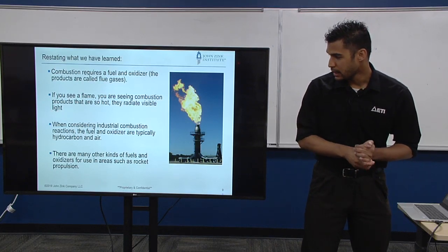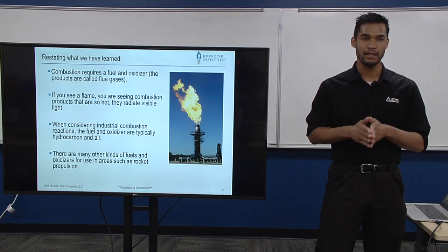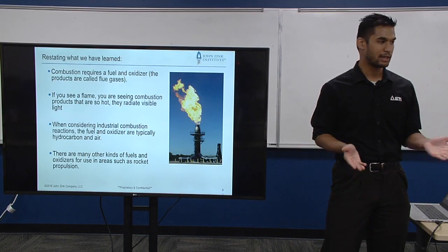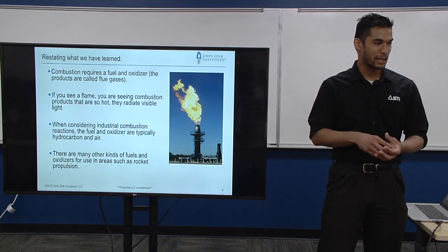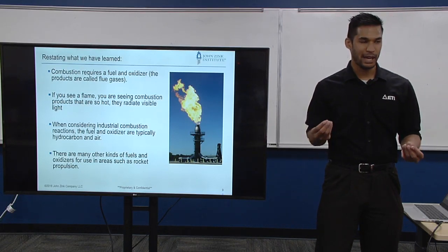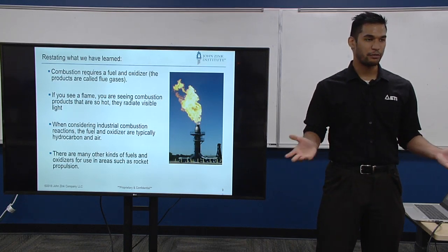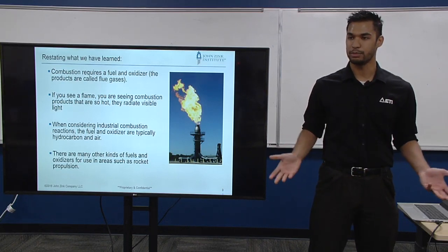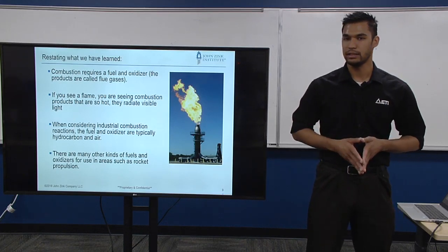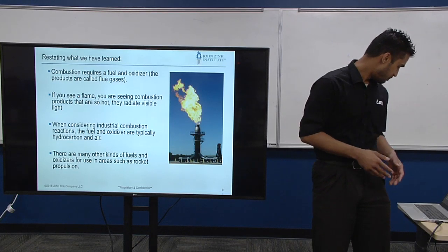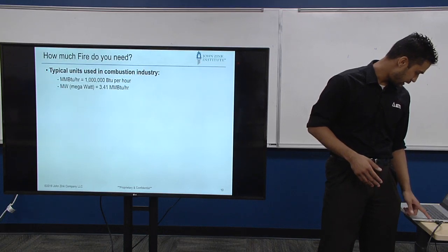Industrial combustion. You have to understand the reactions that are going on in the background because different fuels create different products. If I'm burning hydrogen, I'm not going to have any CO2. If I'm burning an unsaturate and I raise the temperature really, really high in my combustion process, you might have some polymerization even going on at the burner tips. You can have a lot of odd mechanical failures if you overheat a process. So understanding the differences between the fuels and why we're burning them is critical in combustion equipment design. So I've probably repeated myself on the same subject, so let's dig into the lingo.